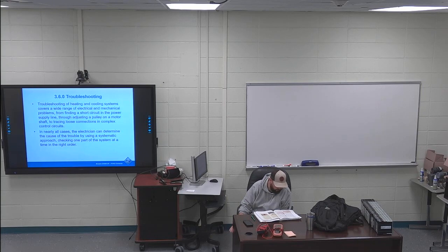Troubleshooting, page 32, second warning on the page. The last two sentences are highlighted. The capacitors used in motor circuits can hold a high voltage charge after the system power is turned off. Always discharge capacitors before touching them. So capacitors hold a charge. Make sure you're discharging them if you're pulling them out or messing with that stuff.